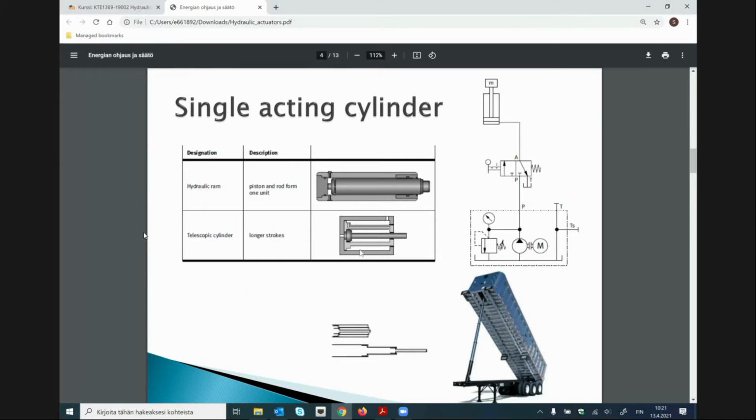So in this telescopic cylinder, you have many pistons put in a small package, and when the first cylinder is fully extended, then the next one, which is inside, starts extending, and so on. So they all the time become thinner and thinner and thinner, and also you get less force, but the highest force normally it is needed in the very beginning, and that's the place where you have also the biggest diameter in the cylinder, so it makes sense.